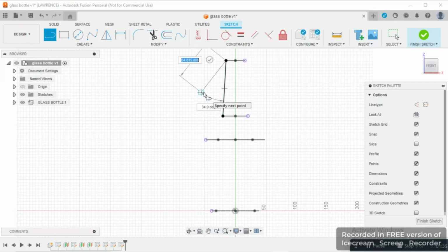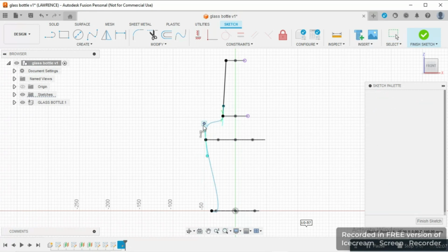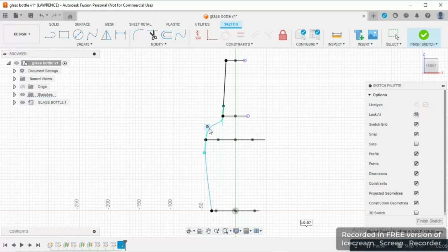Okay, so we then activate the Fit Point Spline command. Start from the bottom point and select the next 2 points. Then you can press the Enter key or mark the green check. We'll select the spline handle and adjust it until it fits to the already existing line. This will ensure our guide rail is continuous and treated as one line. Next, we can select our spline's point, the handle, and adjust it to our desired shape. We can always edit, so that's one of the advantages of using this technique.